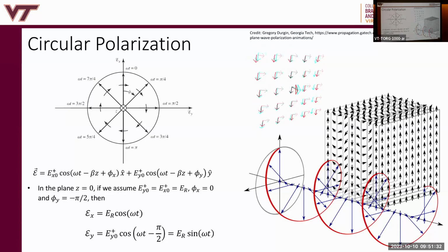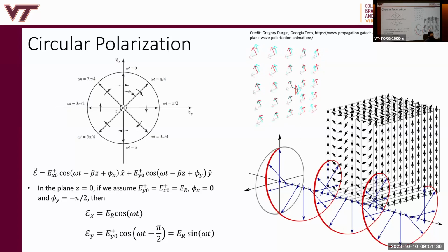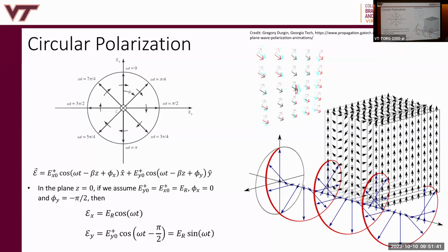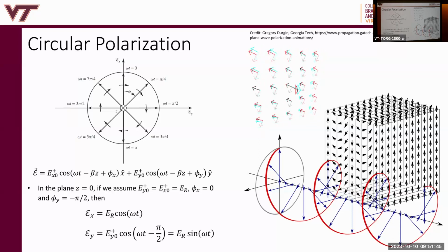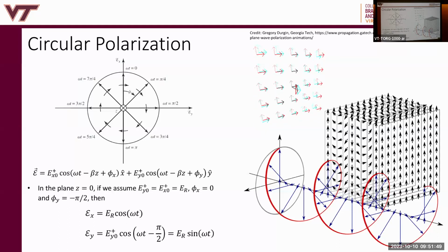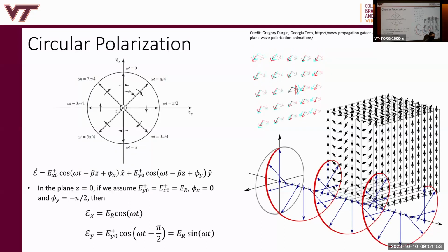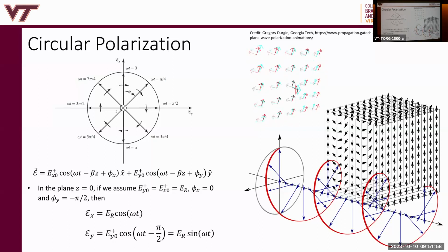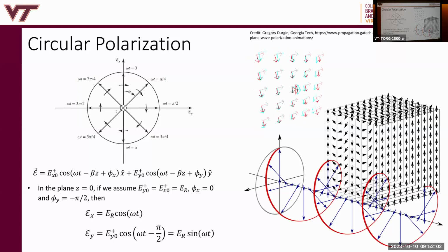So plane wave is always TEM? Plane waves are TEM modes, yes. Yes, there are uniform plane waves where the phase and amplitude are uniform. There are plane waves, TEM modes, which at least the phase has to be uniform. If the phase is uniform, the wave front is defined by the phase on that geometric entity, right? There are cylindrical waves, spherical waves, but all of these mean that the phase is uniform along this particular geometry. Good question.